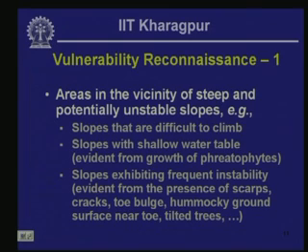Areas in the vicinity of steep and potentially unstable slopes are going to be more vulnerable to landslides, and these areas include slopes that are difficult to climb. It is just a rule of thumb: if you find a slope difficult to climb, you can consider it a slope where you might get landslide activities.